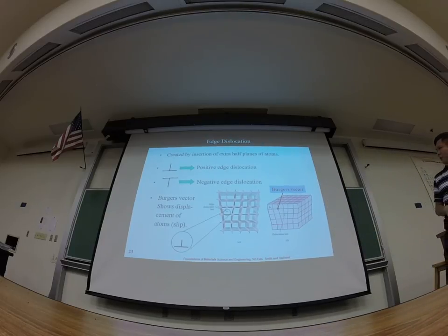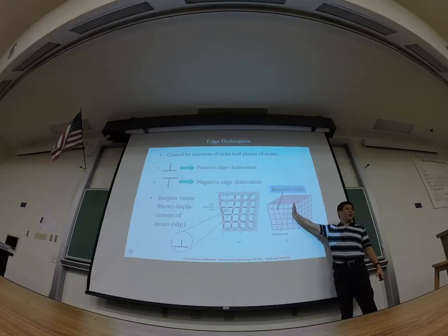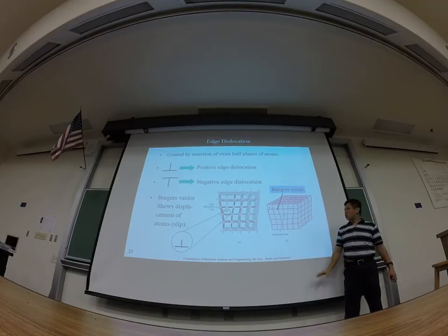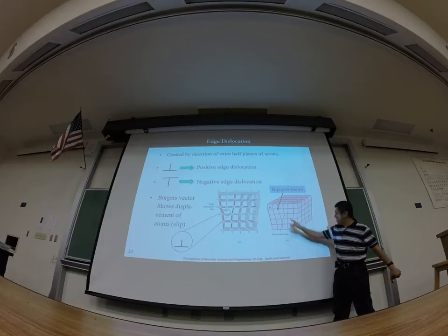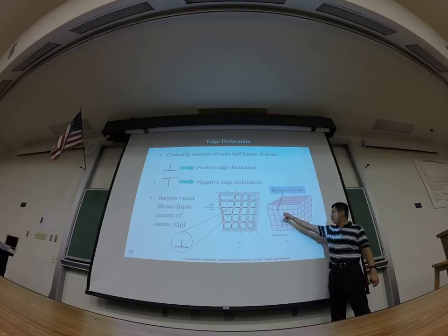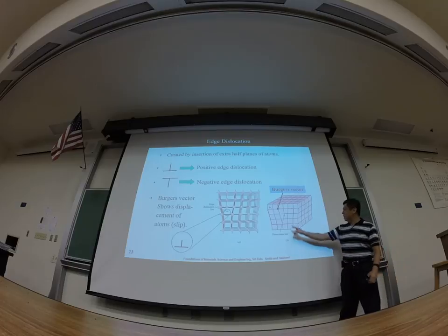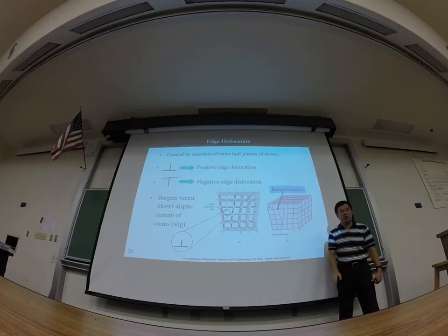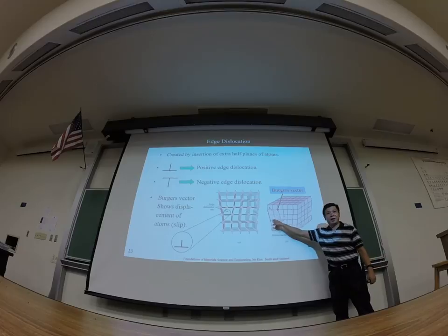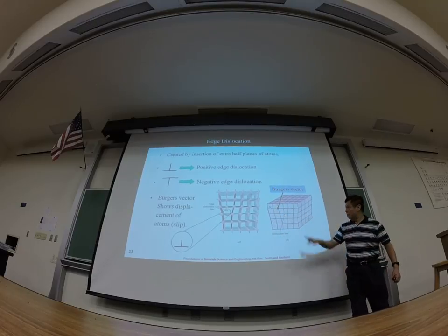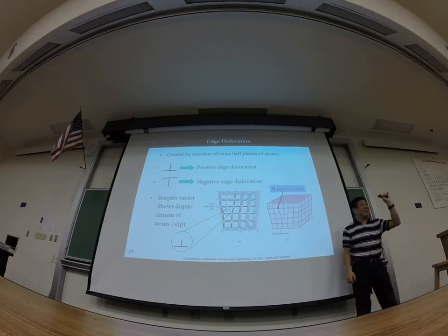The edge dislocation is very easy to understand. Think about that one. If you think about a perfect crystal, under some of the deformation process, some of the crystal planes will be shifted against each other. For example, originally you should have this line, right, repeated in 3D periodicity. But indeed, because under some deformation process, some of the lines were missing. In that case, if you compare the density here and the density above, they are different. Between them, there is a translocation, kind of like a transition area. Those areas will have the line defects.